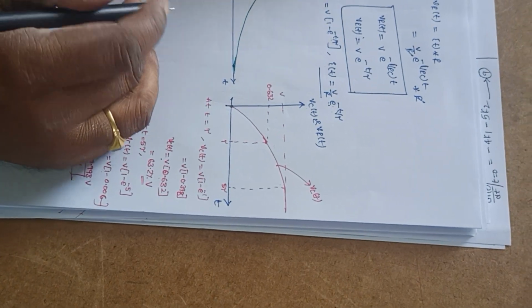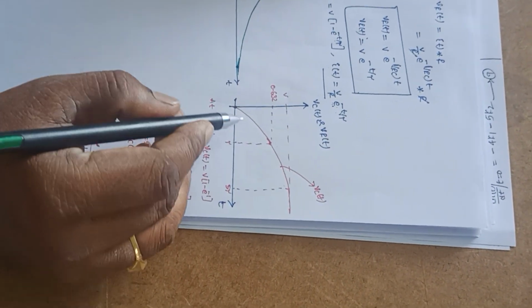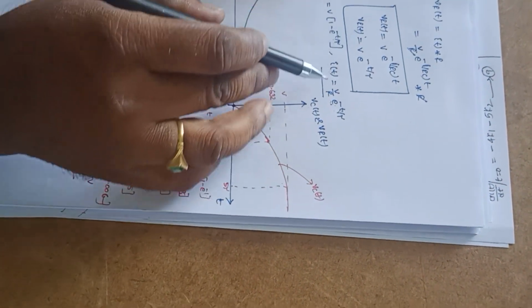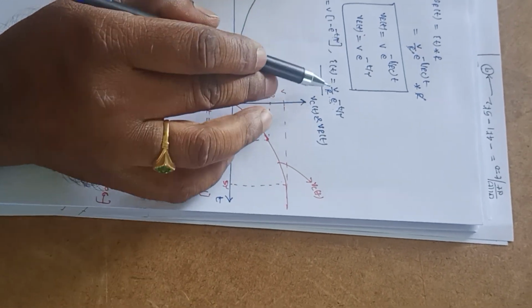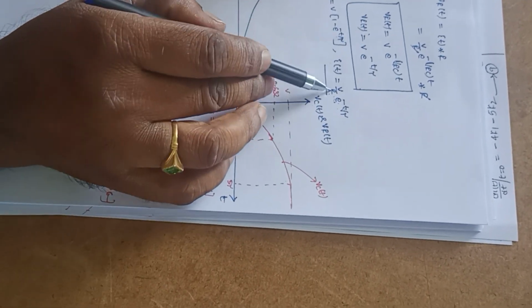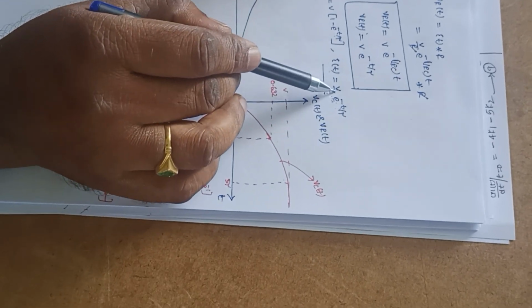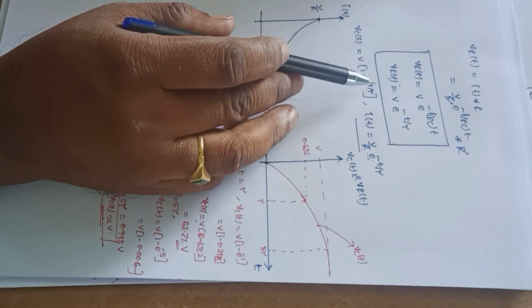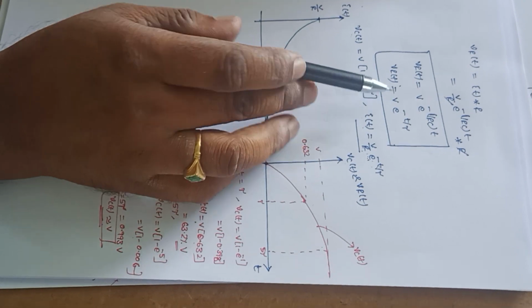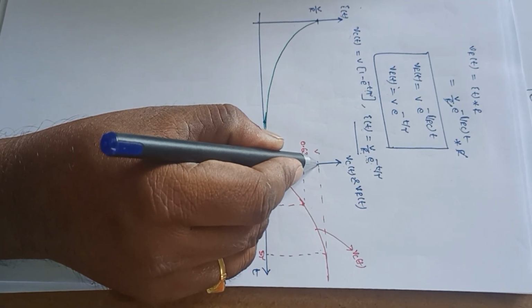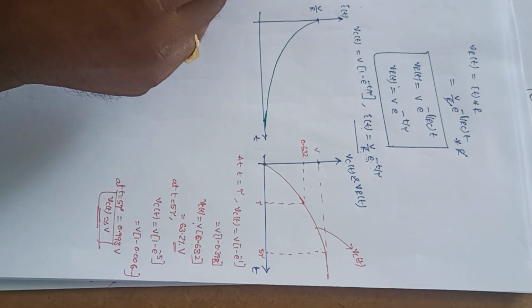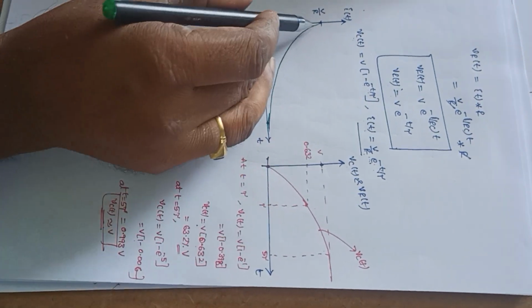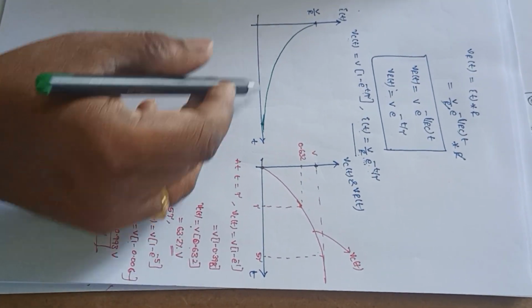Now the I of t curve is over and Vc of t is over. Let me draw this Vr of t. This Vr of t and this I of t are both exponentially decaying functions, except the magnitudes are different. In I of t the magnitude is V by R, so it starts from V by R. But in Vr of t the magnitude is V, so it starts from here, and it follows the same waveform as I of t.